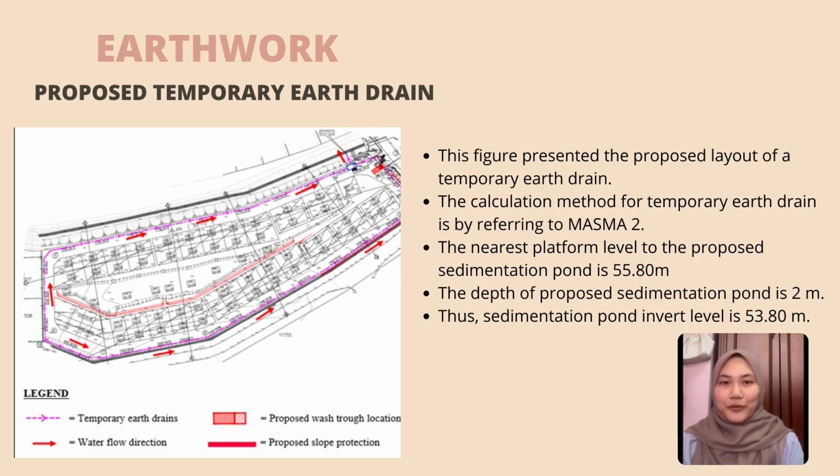The nearest platform level to the proposed sedimentation pond is 55.80 meter. The depth of the proposed sedimentation pond is 2 meter. Thus, the sedimentation pond inlet level is 53.80 meter.